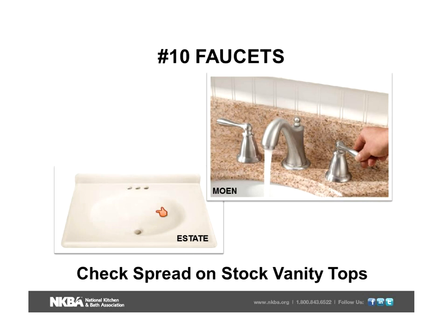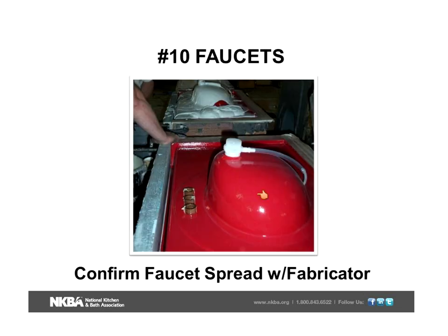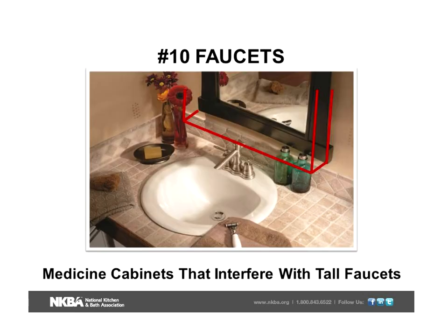Now we know right within that lumberyard home center we may have pre-made solid surface cultured marble tops. The same is true here. However, when you start having one fabricated, remember, and this is the beginning of a cultured marble top, that has to be blocked in advance. And unless you tell them otherwise, they're probably putting these for 3-inch spreads or 4-inch or whatever we may have. Whatever the standard is for them, that's what they're going to use. So you can see it's very easy to change this, but they have to know ahead of time.